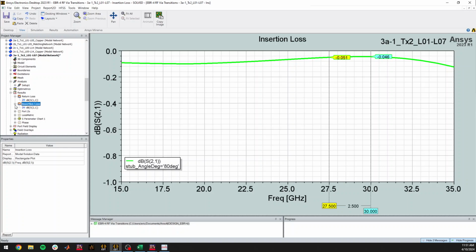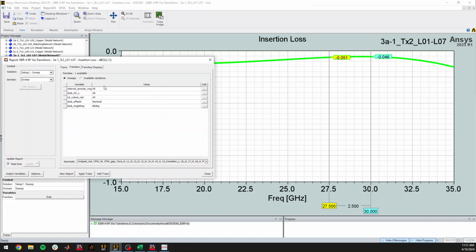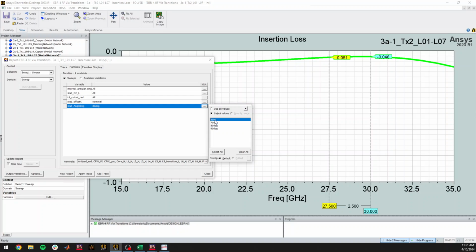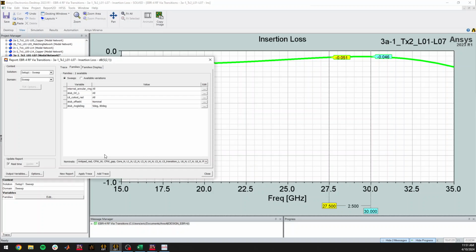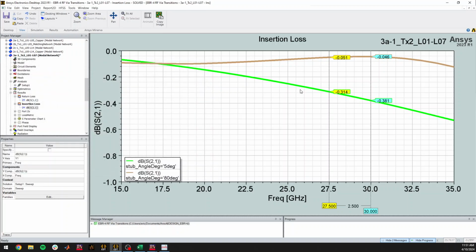And likewise for the insertion loss, what I'm showing here was the original design, so that's 0.3 or 0.4 dB of insertion loss. But with that matching network added, we're getting under 0.1 dB, which of course will actually be just 0.05 dB, most likely not because of manufacturing reasons or copper losses and things like that. But this is a very good sign as to the general health of the design.